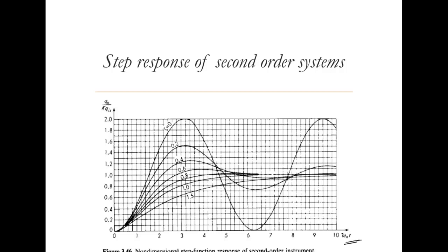Generally they appear together in the complementary function and the particular solution of the differential equation, so we would generally use omega and t together. So this is how the instrument actually responds. It oscillates, goes from maximum to minimum and oscillates, or in some other cases it oscillates to some extent and then almost damps out. But there are instances where it just follows the input. All these vary with respect to zeta. Now, the parameters that we have are zeta, omega n, and k, which we have already put up here. So what we are controlling is actually zeta and omega n.